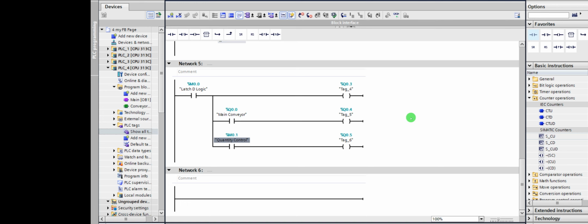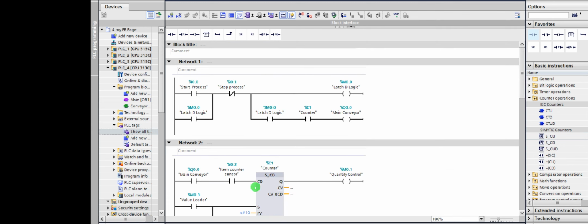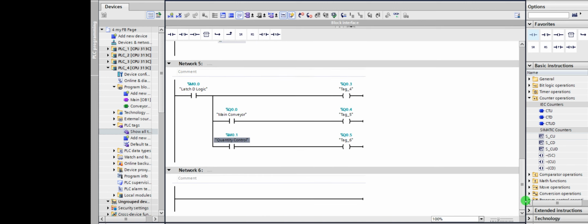There's what we call a block, let me show you the block here. Come here, you see block. So you come here, it now creates a function block. Each of your logic should have a function block. This logic we just designed is embedded in one block. The name of the block is conveyor and counter logic, and it is on FC1. So if I create another, FC2, in a complex design you segment them by creating function block after function block.